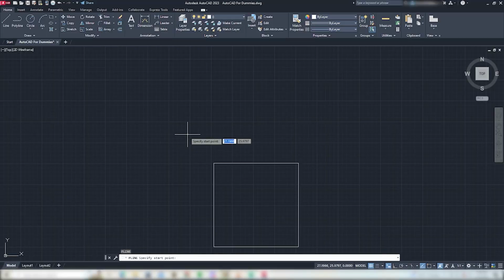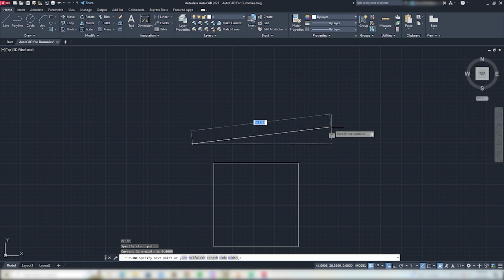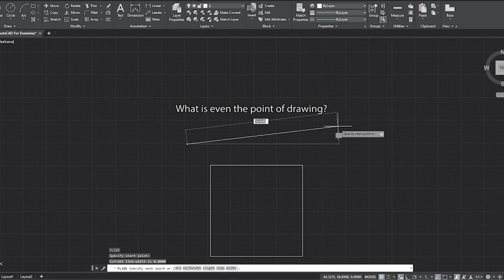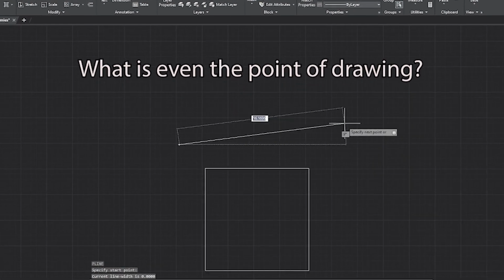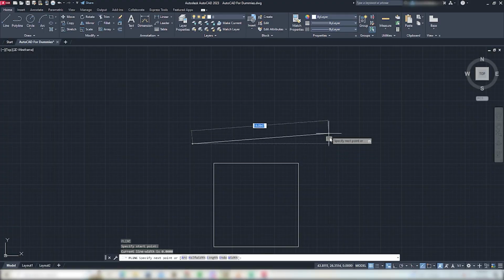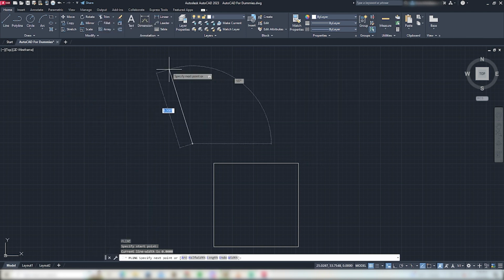If I draw it by hand, by just clicking without the Polar Tracker on, it doesn't give me those green guided lines. Why are we still here? Just to suffer? And now I can draw at different angles. It won't snap me to that 0 angle that I want to be at. I want to be on that horizontal point. Same thing with the vertical plane. It won't snap to that as well.